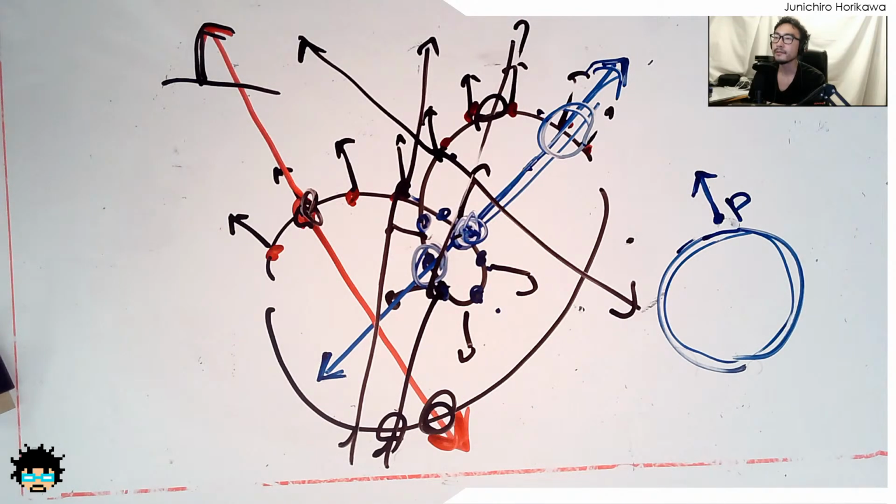I can use the normal direction to offset a point just a bit outside, maybe multiplying with a really low value like 0.01 or something. Okay, so this will be the starting point for the intersection. Then you also need to define the direction, which is going to be N. And in order to use the intersect function, you also need to define the length of this ray. You kind of want to have a really long ray to check if there's going to be any intersect or not. So I'm just going to multiply with 1000 to make it big enough to be able to check really far a distance.